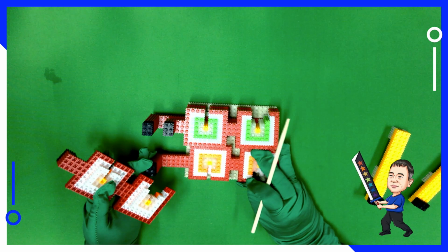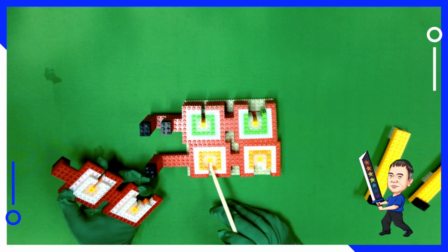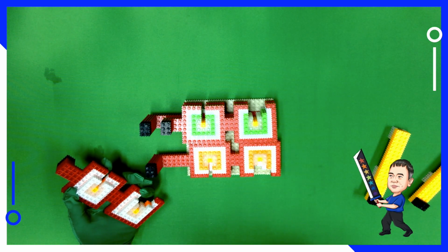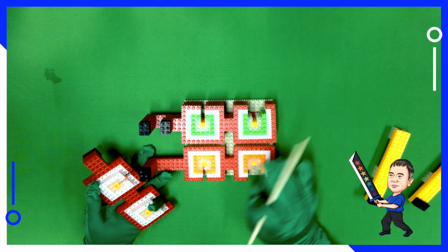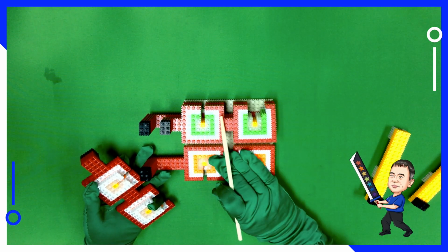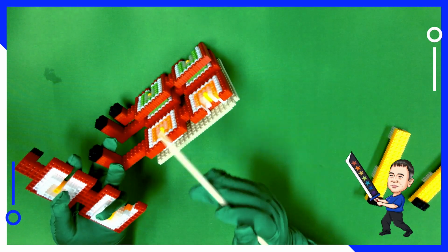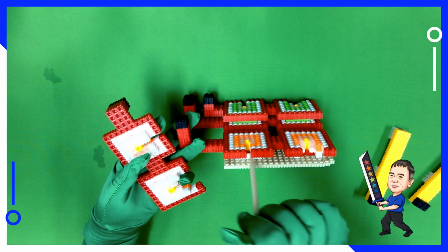So the floating gate is totally covered by the insulator. That's why it's called floating. Then the floating gate will make an electric field to here, and it depends on the control gate. So if your control gate applies a high enough voltage, then the channel here will be open. The channel here will always be open.